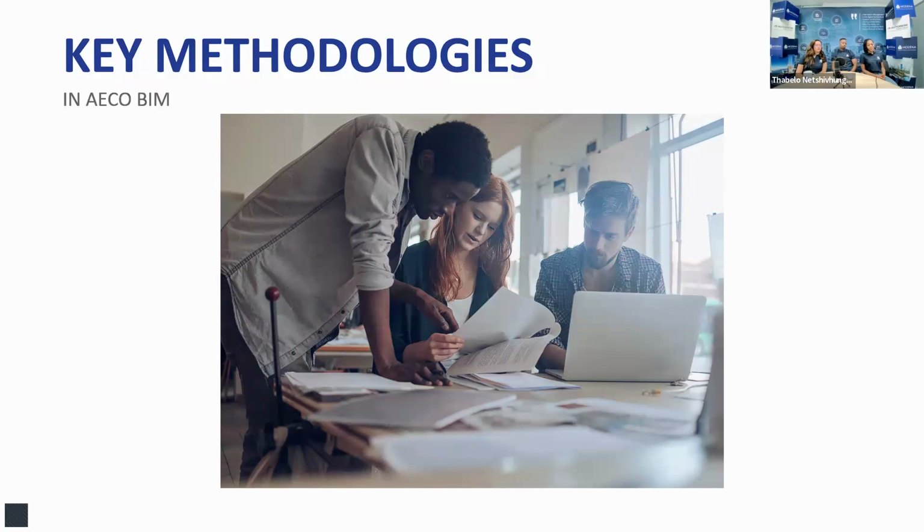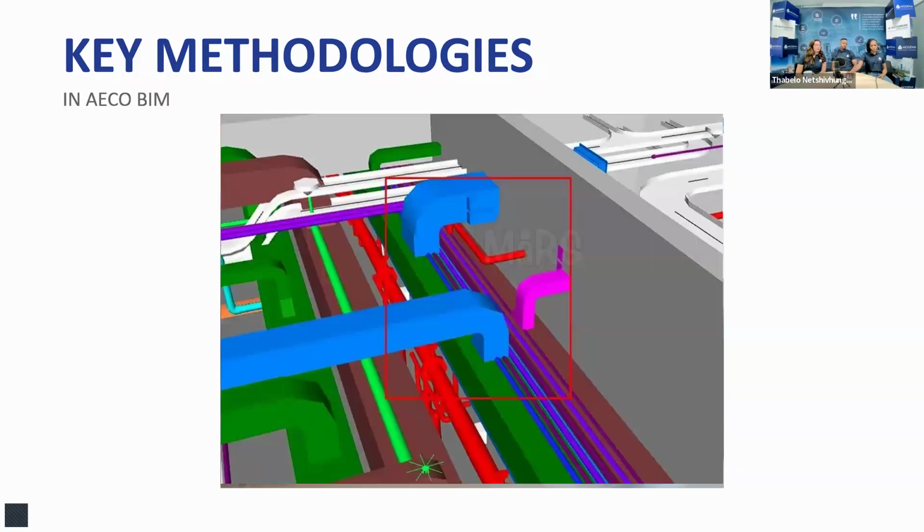Another important methodology is clash detection and resolution, where we proactively identify and resolve conflicts in the models before they actually reach the construction stage. We also utilize tools like Navisworks for automated clash detection and schedule regular reviews of models to address potential risks. This is just a screenshot of what clash detection would look like in any of our clash detection software.